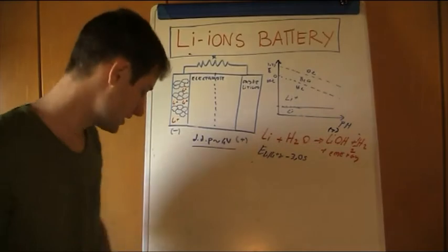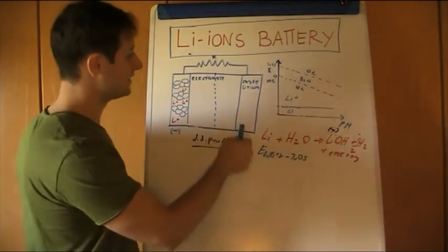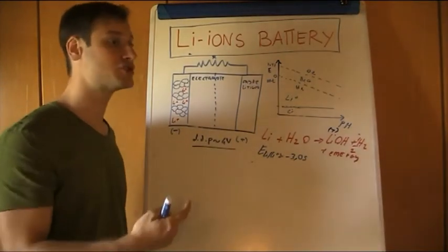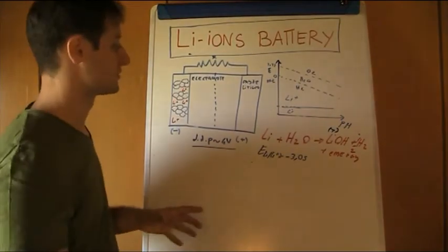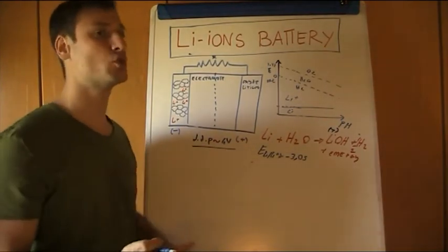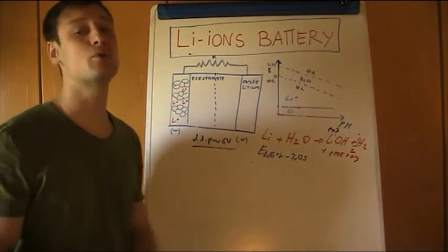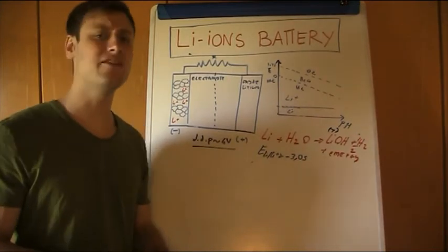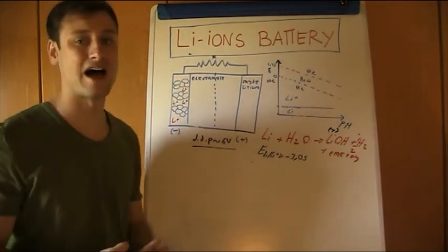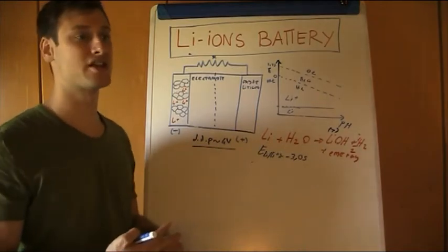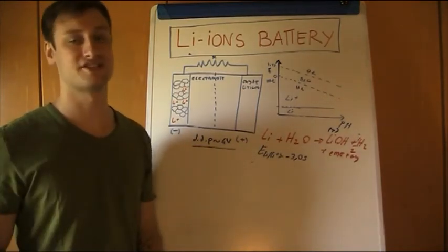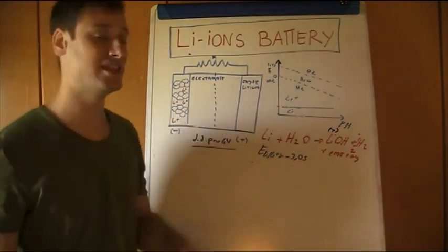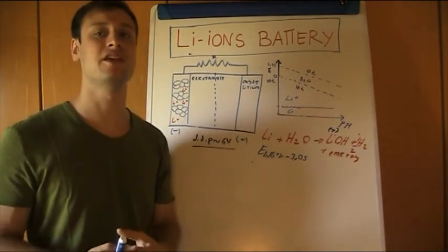our electrolyte. Another hazard connected with lithium-ion batteries, together with the use of specific aprotic solvents and the use of a sealed structure, is also the fact that we need to avoid a too quick recharging process, because it can even cause a short circuit and promote an explosion. And if we are recharging the batteries too fast, or even if we are heating the battery to a temperature higher than 100 Celsius degrees, we can promote the decomposition of the positive electrode, the decomposition of the lithium oxide, that can release oxygen and even cause explosion.